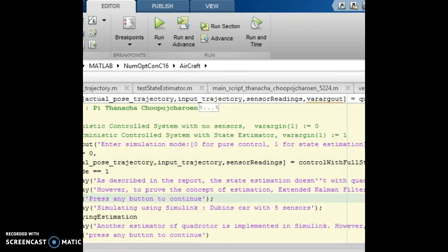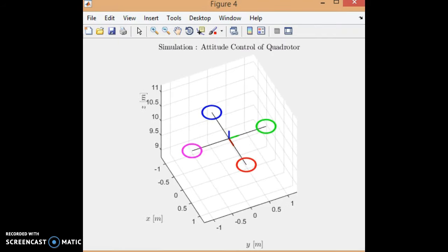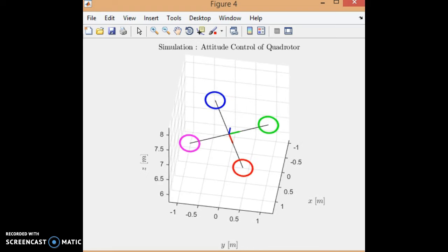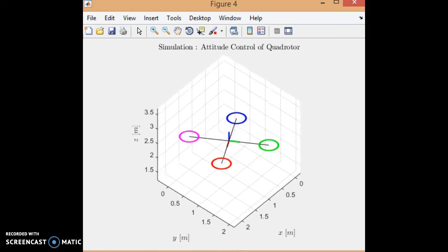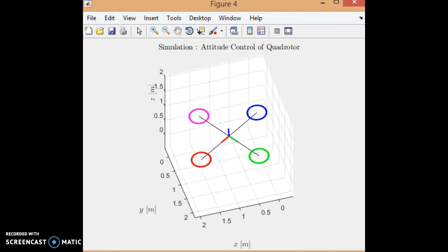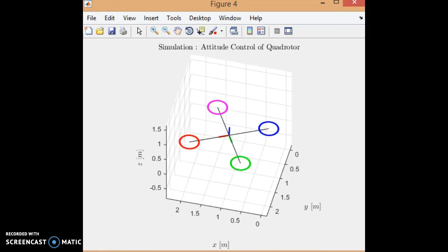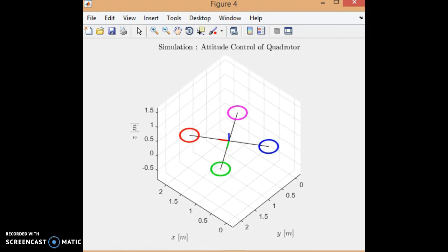This one is called hover control. Now, the robot will start at one specific position and orientation. We have to define a control policy such that the robot will navigate to the desired position and the desired yaw angle. Okay, we basically assume that the desired roll and pitch angles will be 0, 0. Otherwise, the robot will move around. That's why they call it hover control, right?